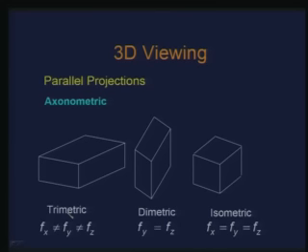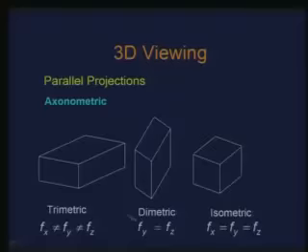So, what we have is a combination of rotation and translation added to the orthographic projection, where we can have 3D viewing containing the three-dimensional aspect in it. Depending on the type of foreshortening we obtain, we have isometric, dimetric or trimetric transformation. Next time we will proceed further from here and talk more about 3D viewing. Thank you.